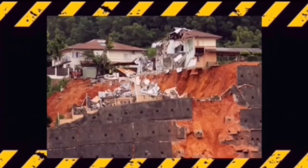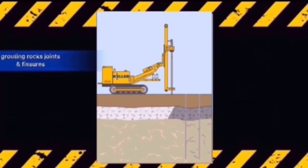Secondly is landslide. Landslide occurs when the force acting down the slope exceeds the strength of the earth material that composes the slope. To prevent landslides, grouting of rock joints and fissures needs to be done to reduce the flow of water along the paths and discontinuities in the rock.